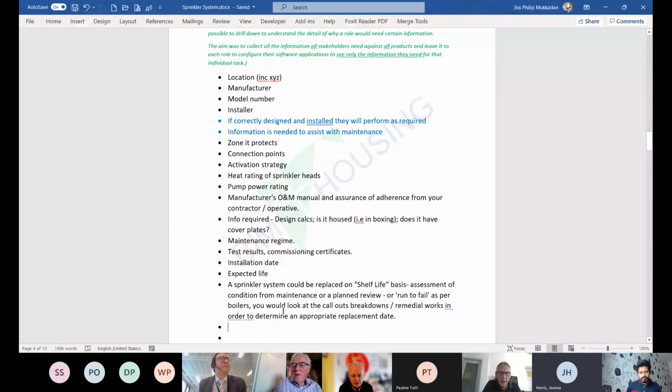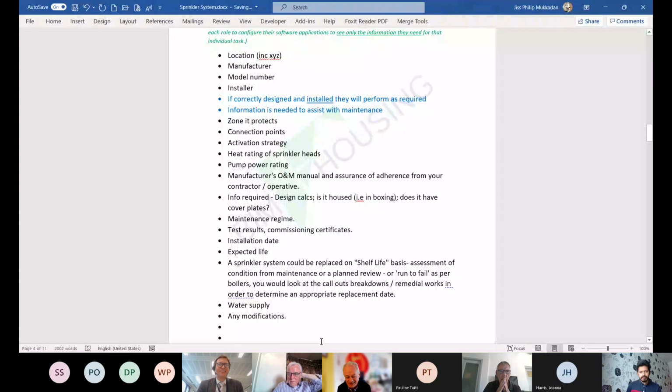I might be interested. Sorry, George. Yeah, drop us a line if you're interested. I'm updating Guide M, which has the life data in it. Currently, I'm just quickly looking: the sprinkler system main pump sets are 20 years, the pipe work and the heads are 30 years, and for valves, it's 25 for wet and 20 for dry. That doesn't sound wrong, and you may find that they're fine after that time, or actually they don't even last that long. Indeed.